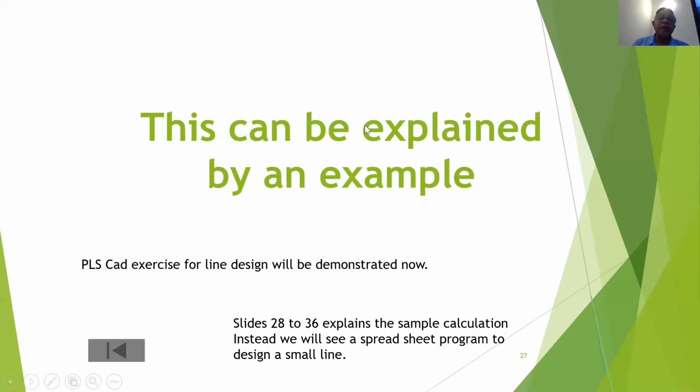This can be explained by an example. I am coming to that. We have a spreadsheet program for calculating and deriving the tensions using Newton-Raphson. Before that, I'll hand over to Vinavi to demonstrate the PLS-CADD exercise for line design.